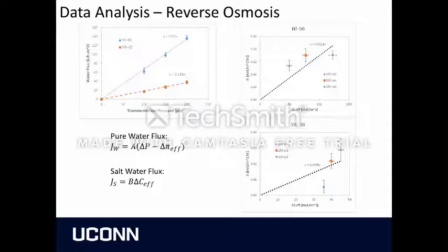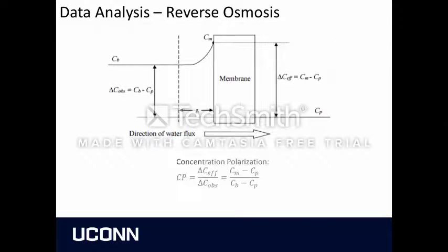As with forward osmosis, we can also explore the concentration polarization phenomenon for reverse osmosis systems. In reverse osmosis, there is an increased solute concentration on the feed sides of each membrane, raising the osmotic pressure. This means a larger pressure must be applied to produce the same flux, resulting in larger energy costs.